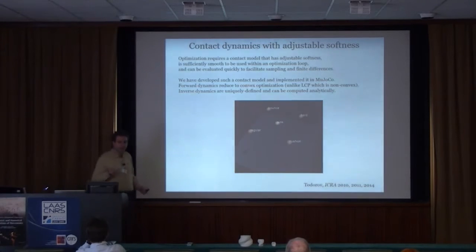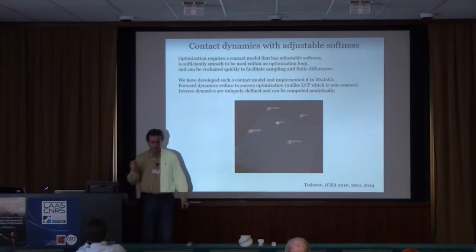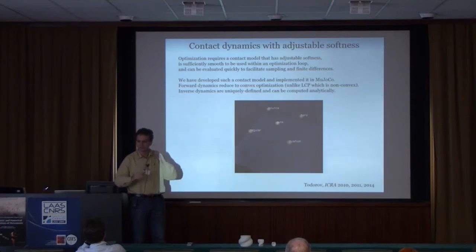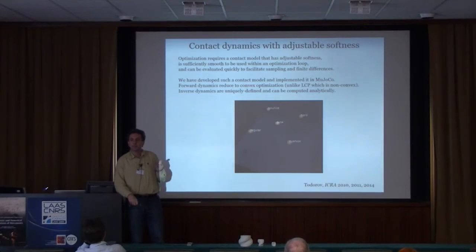In particular, all the modern models come down to an optimization problem. So both this simulator and all the simulators behind your favorite first-person shooter games don't actually have an analytical formula for what the equations of motion should be, even instantaneously. Instead, they solve an optimization problem at every time step to figure out the acceleration of the system in response to some applied force. And then they keep going.